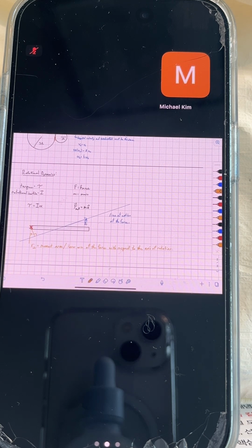Okay. And so then we said, all right, now what we're going to do is define the torque as just whatever that moment arm is times whatever our force is. Okay. And then after this, we talked about how this is definitely one way to calculate it, and this is really how we define torque, right? And so when people talk about the lever arm for a force, this is what they mean, okay? In particular, they don't mean the distance from my axis of rotation to where I'm actually applying the force, okay? It's always, again, this distance from my axis of rotation to the line of action of my force.